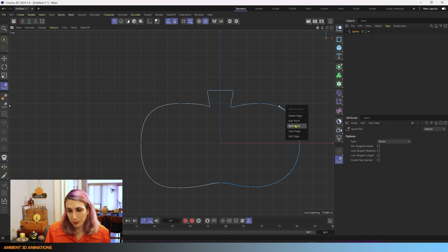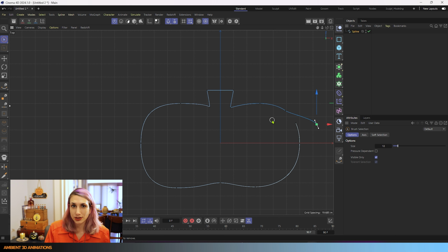split at a split point. So I'll show you what the difference is between this. So I'll add a split point here and I'll hit Escape. Now what you'll notice about the normal point that we added is that it's all connected. If we add in a split point, you'll notice that these 2 points aren't actually connected anymore. That's the difference between just adding your typical point and adding in a split point. So that's just good to be aware of while you're working with this tool.